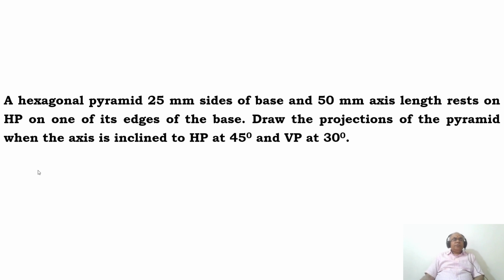In this video, we are going to take up one more problem on projections of solids. How to analyze and solve this problem by using the sketchbook. The problem reads: a hexagonal pyramid, 25 mm sides of base and 50 mm axis length, rests on HP on one of its edges of the base.